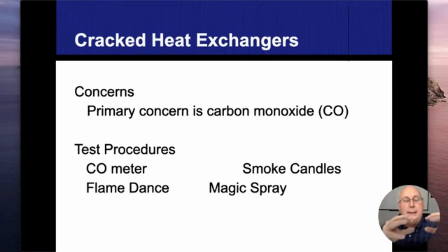But as it goes over the heat exchanger, if there are any openings in that, then that heat is going to blow to the inside of that heat exchanger. If it's able to touch the flame, it changes the flame from blue to either orange or bright red. It's pretty cool when you see it happen. So you spray like 6 pumps in there, and it goes into the flame. The flame goes from blue to red and then goes back to blue again. The only way for that mist to get there is if we have a hole or an opening into that heat exchanger.